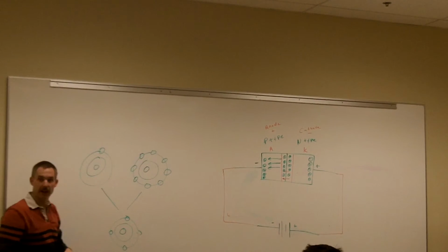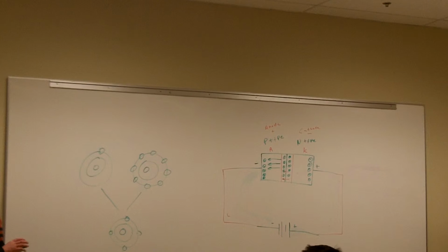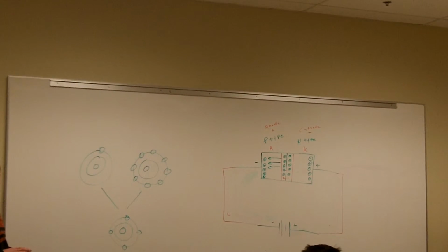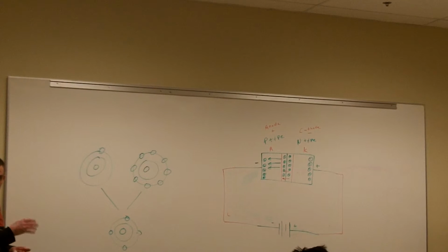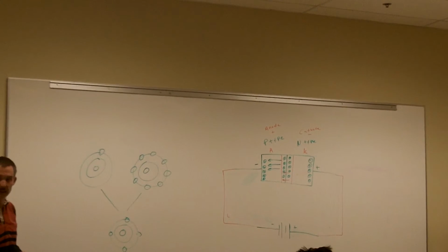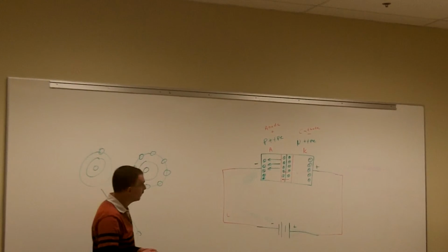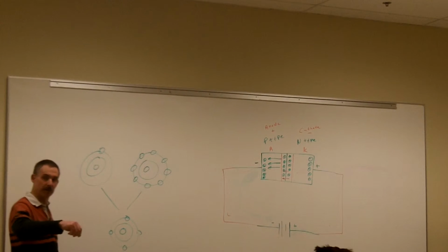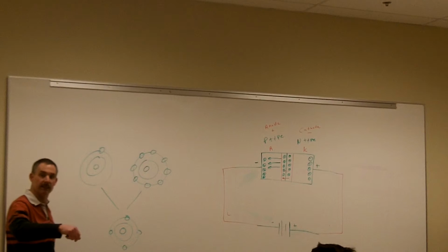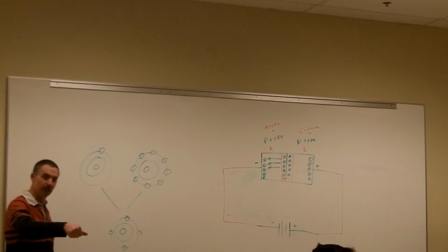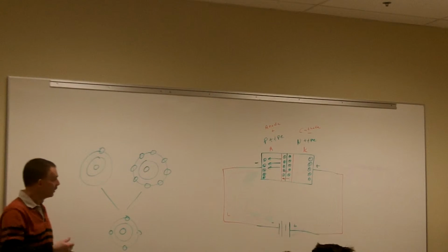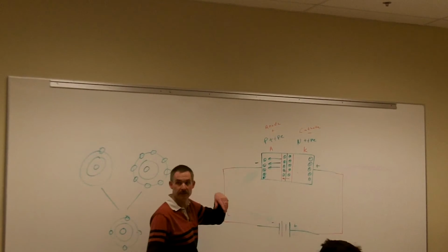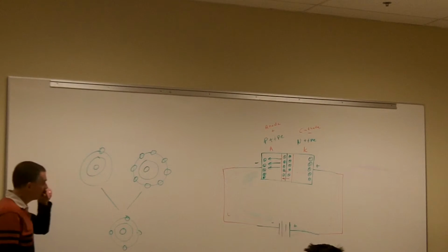So yeah, you're right. It will eventually burn out the LED because you're in reverse biasing and then in a reverse breakdown of the diode, so it's actually destroying your LED. But if you just have a low voltage, like we did in labs, remember, if we had our LEDs wrong, the light didn't light up, but then we turned it around and it lit back up. That's because we never put enough voltage on there to do that reverse breakdown. Okay.